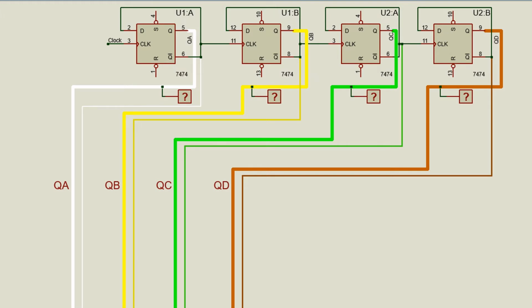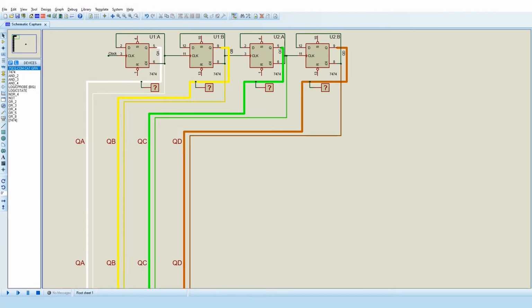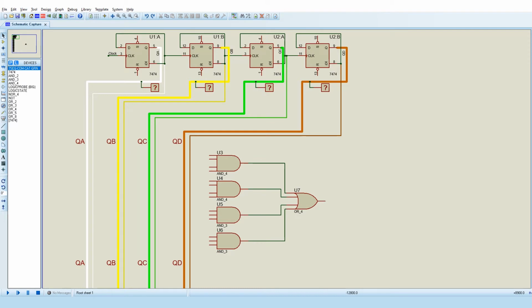So I do that a lot in my designs. So now we're going to implement segment A. Now segment not A, the expression that we had 2 4-input AND gates and 2 3-input AND gates. So if we use an OR gate, that'll only give us the output for not segment A. So we put a NOT gate on the end, and that'll give us segment A. But we can combine those 2 into a NOR gate, which I'll do later.